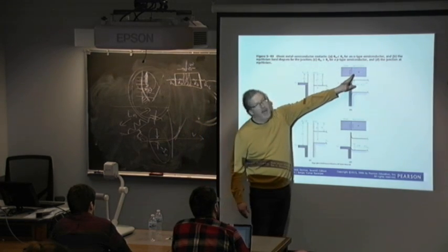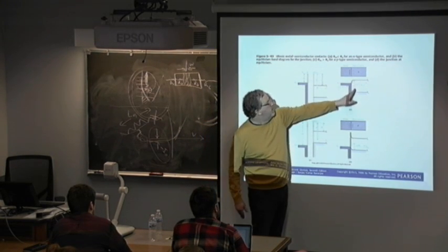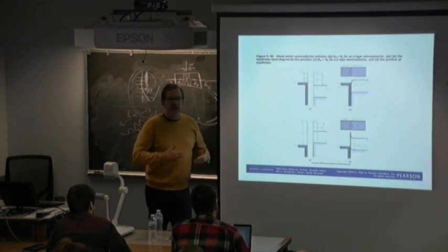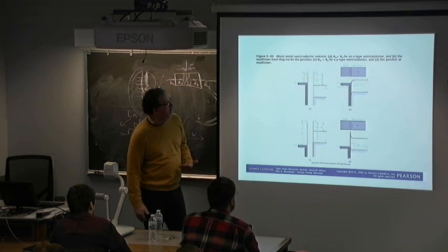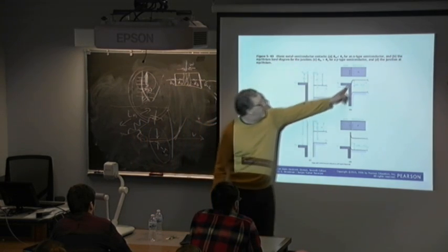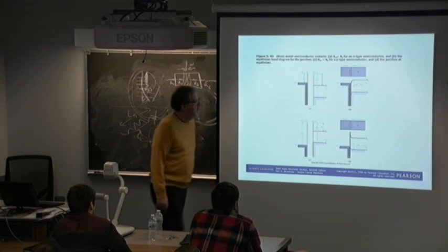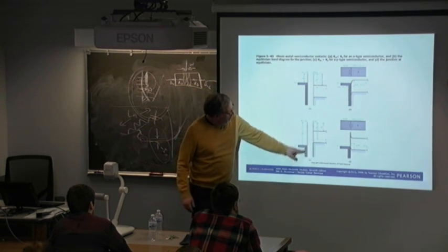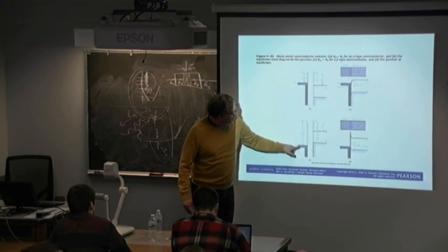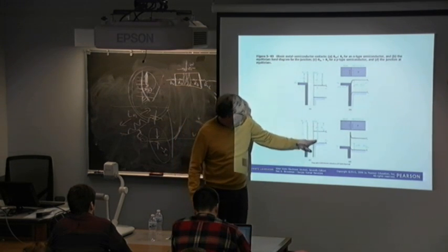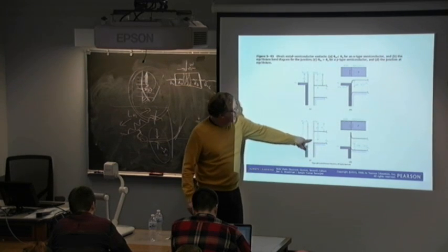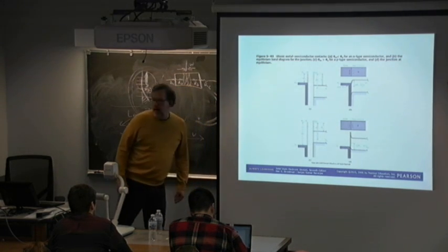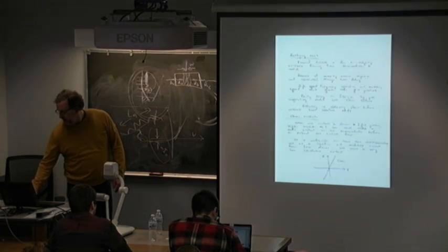I accumulate electrons, which are the majority carrier, at the surface, the bands bend, and I have lots of electrons to corral because it's the majority carrier and there are plenty of them, and they pile up within a skin depth. Right. You can rationalize it out the same way with the holes. I need to lower the Fermi level of the p side with respect to the electrons, so the only way I can lower it is to accumulate holes. So holes push everything down, and I get this very small.